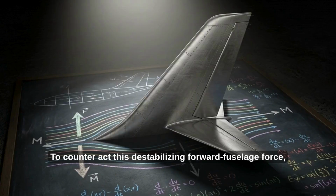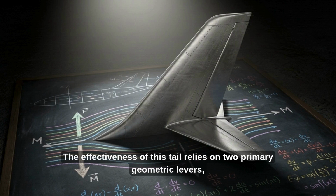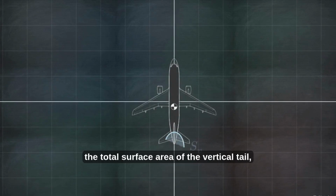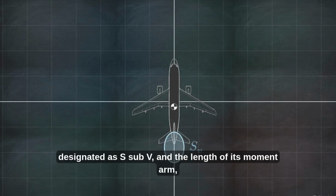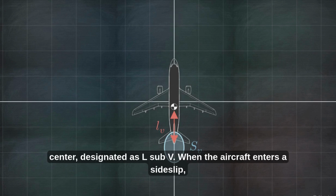To counteract this destabilizing forward fuselage force, engineers rely on the vertical stabilizer at the rear of the aircraft. The effectiveness of this tail relies on two primary geometric levers: the total surface area of the vertical tail, designated as S sub v, and the length of its moment arm, the exact distance from the center of gravity to the tail's aerodynamic center, designated as L sub v.